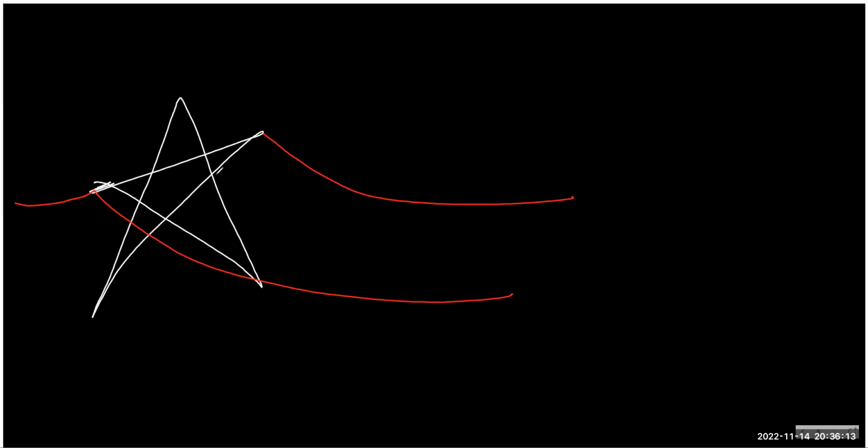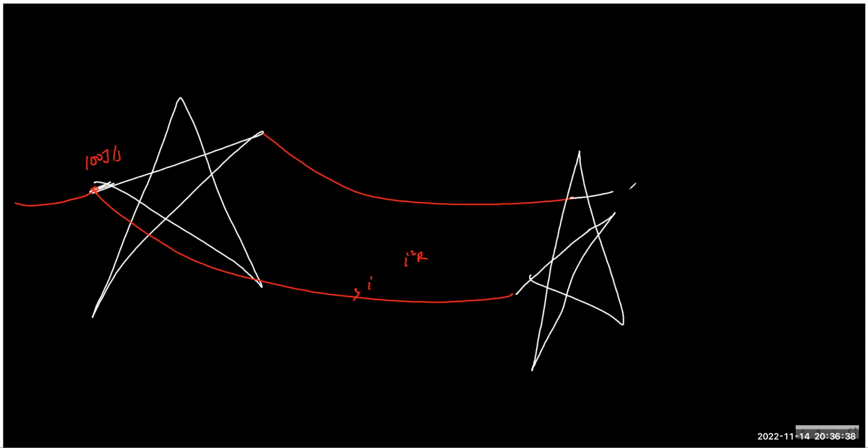But the problem is this cable will have some resistance. So if it carries current I, then the power loss will be I squared R. If I'm sending, let's say, 100 joules per second at this point, and there is a loss, the next tower will receive a lower value, which is not good, right? Yes, sir. So we want the power to reach the city or whatever location without much loss. The loss should be almost negligible.